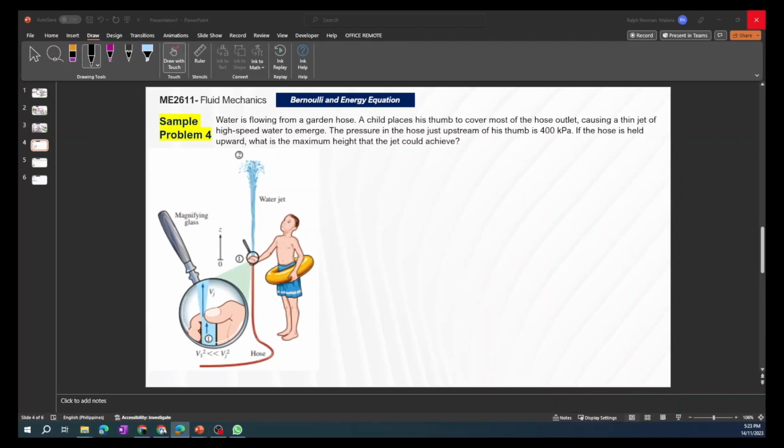Okay, so finally we go to Bernoulli and the energy equation. I know there's a lot of formulas there, but technically there's one formula that you should already know, which is the Bernoulli equation at two different points, mainly in energy form. So that's going to be P over density g plus V squared over 2g plus z, or H, which is constant. And for steady flow along a streamline and in two different points, we could rewrite that equation to